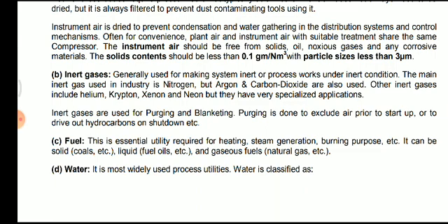Inert gas is used for purging and blanketing. Purging is done to exclude air prior to start up, or to drive out hydrocarbons prior to shut down.